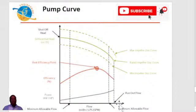By the time we move to the technical evaluation of the vendor data sheet, you will see what API 610 says with respect to the margin, or the percentage, that has to be between your rated flow and your best efficiency point flow rate, or between your best efficiency point flow rate and your preferred operating region.